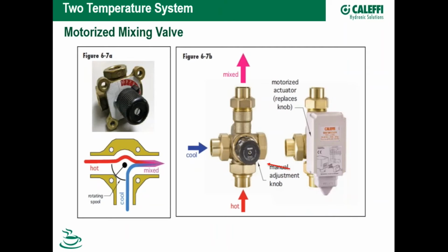The next of my options is a motorized mixing valve. So there's no thermostatic element. It's a mixing valve whose position is going to be driven by an electric motor. So one of the things that you have here is, in order to make this work, not only do I need the mixing valve with the motor, but I also need a control to determine where the mixing valve has to be positioned and to actually position that mixing valve.